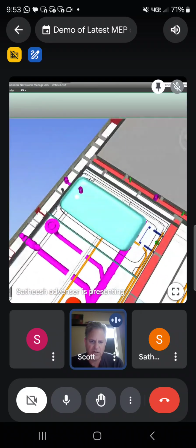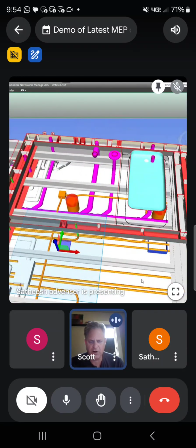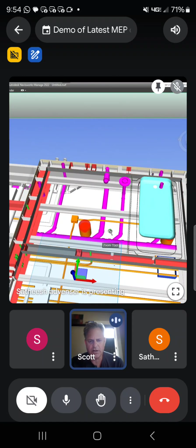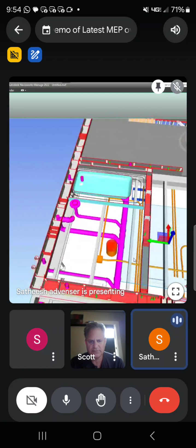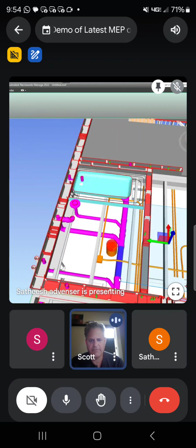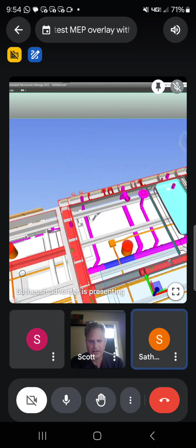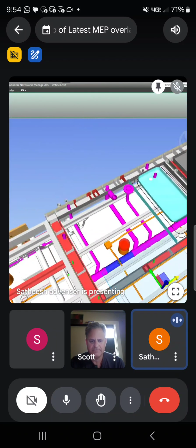Now, I see the way you're running that drain line. How much fall is in that pipe, the main line where you're dropping back down to the first floor? Did you have enough room in there to get that fall? This pink line? Yep, because there is a riser. Okay, so then you're falling down there. Got it.